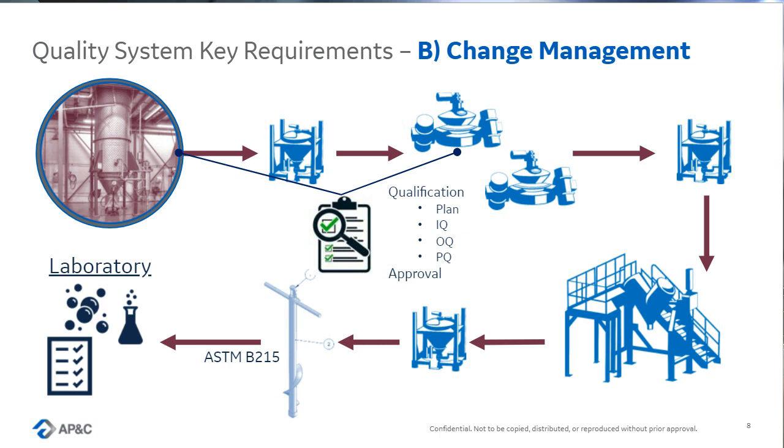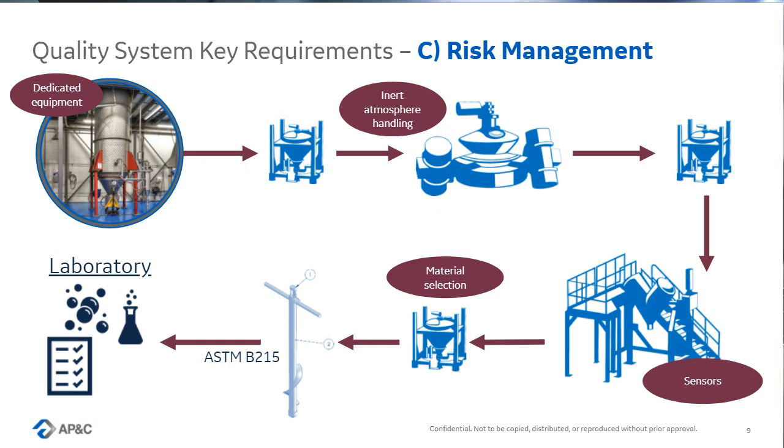which is risk management. Obviously, when we're dealing with powder, even more so titanium, which is vastly used in the medical industry, we're talking about material that is reactive. Some sizes are even classified as flammable solids. So there's some risk in handling those powders.